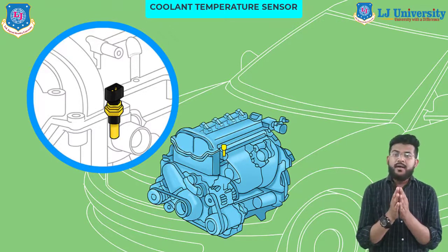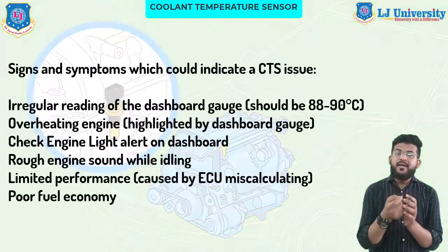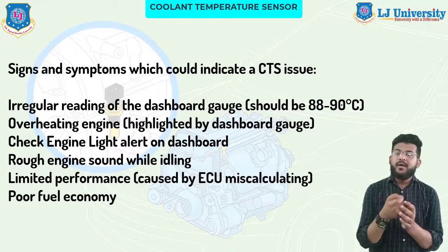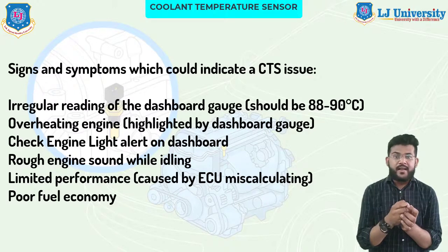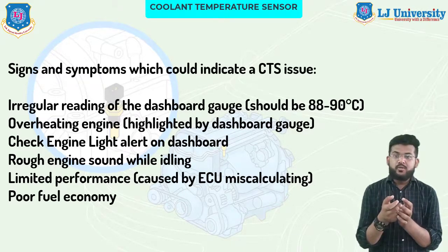Here I have given the other signs and symptoms which can also indicate coolant temperature sensor issues. First is irregular reading of the dashboard gauge. It should be between 80 to 90 degrees centigrade when the engine is warmed up. Now overheating engine, as highlighted by the dashboard gauge. So check the engine light alert on the dashboard. Thereafter rough engine sound while idling and limited performance. It is caused by the ECU miscalculations and it is giving the rich mixture.